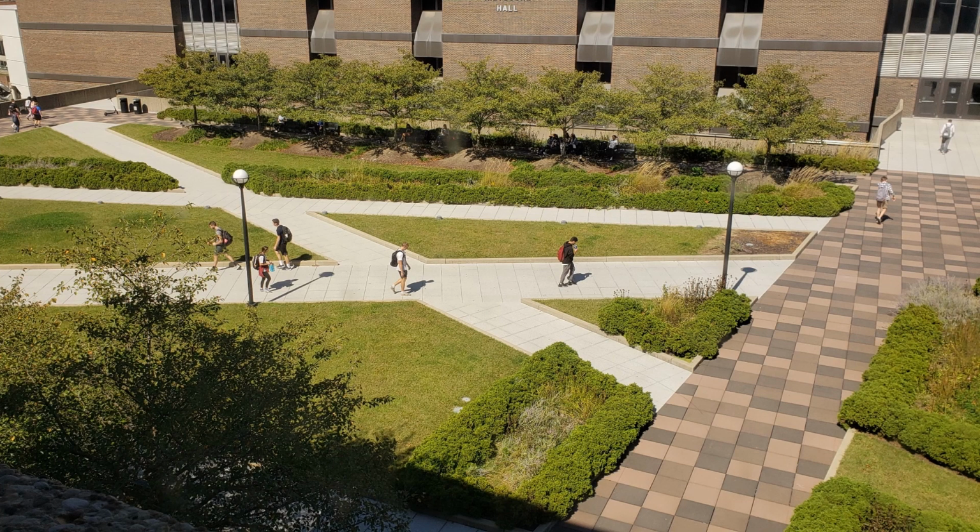Okay, and I'll go back to this image again of the roof of Zimmer Auditorium as a case where, say, the students walking across this roof, for instance, would be considered a live load per ASCE 7, and then all of the greenery and the landscaping elements would be considered part of the dead load.